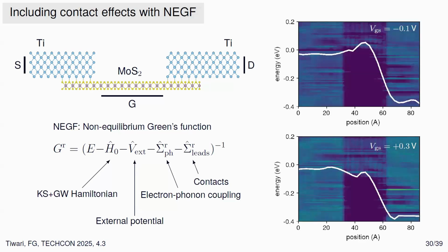In practice, what we can do now is to study the density of states of the system and the potential barrier that the electrons see as you change the gate to source voltage. Here, for example, in this case, the device is off. And as soon as you apply a larger potential, the device becomes on because the electrons can tunnel through to the other side. So it is a standard kind of thing that you can calculate. The difficulty is to calculate in a predictive way, reaching the same level of accuracy that we can for the mobility. So this is a much more complex question.